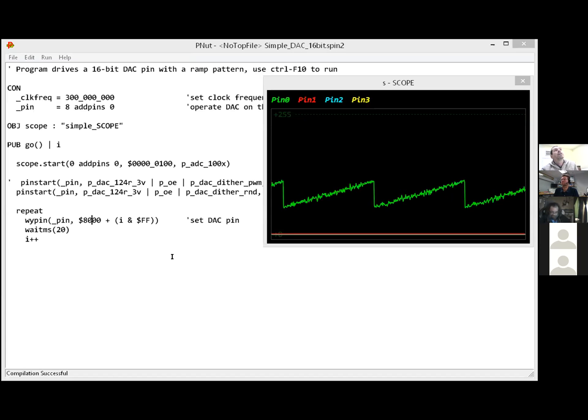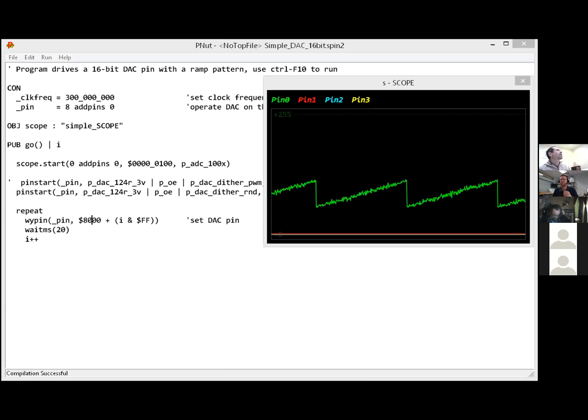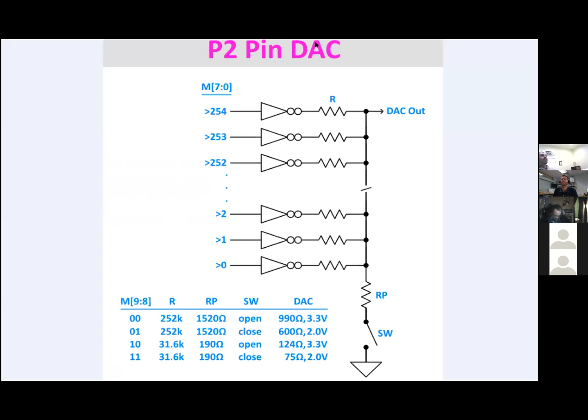Chip, I had a quick question when you were doing just the non-smart pin DAC mode. Yes. When you have all 8 bits filled with ones, are you getting 3.3 volts out? Absolutely, yeah. That's rail to rail. Okay, so there's no level control there. No. Right, yeah, just think what happens. This is all 3.3 volt logic here, right? So when all these things are outputting highs, you're gonna get a 3.3 volt high out of here.